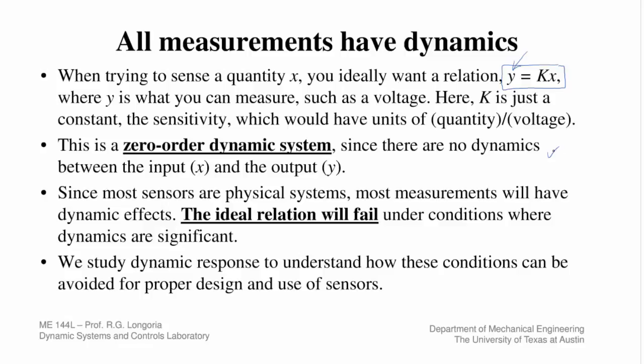And in fact, that's why, for a lot of sensors, they will just report that quantity, the sensitivity, even though inherently the system has dynamics. And we're going to talk a little bit more about that. That's how you want the sensor to be used, in a region of operation where you always have this constant relationship. It's linear and constant.